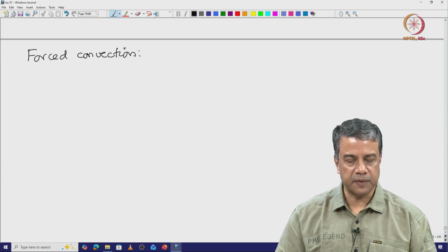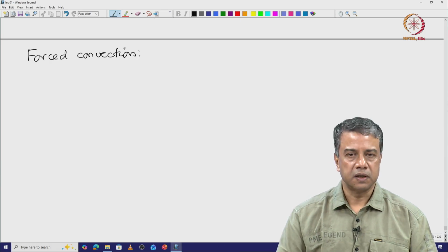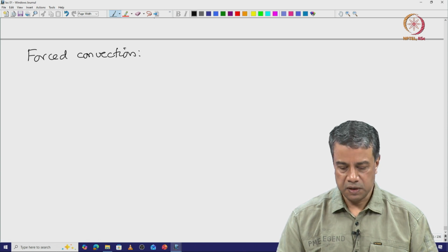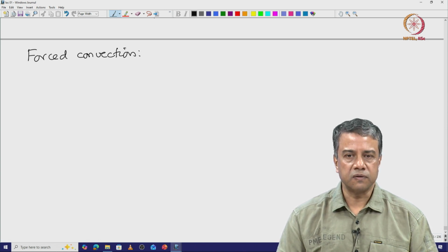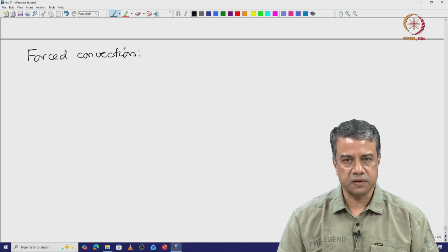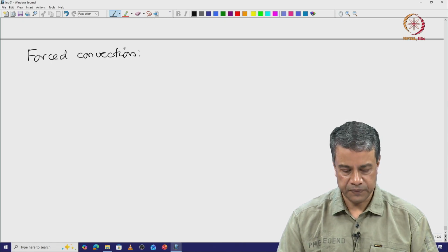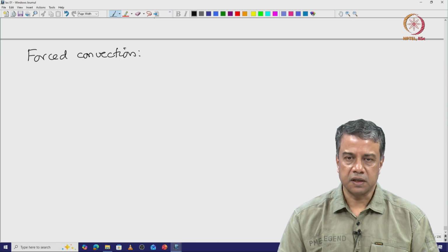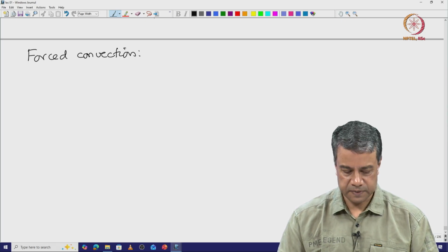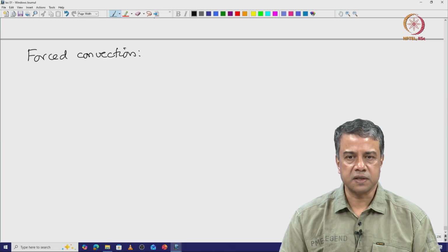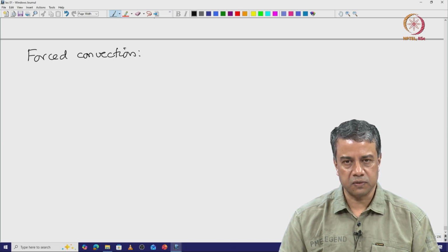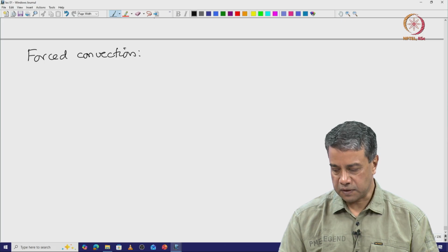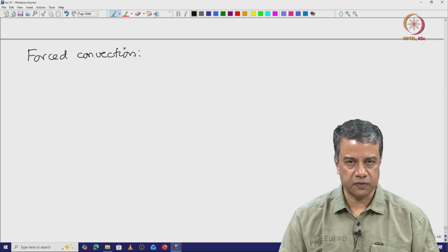In the direction perpendicular to the flow, there is no convective transport. At a surface, the flow is tangential to the surface because of the no penetration condition. Therefore, there is a flow only along the surface, there is no flow perpendicular to the surface. Heat transfer from the surface cannot take place due to convection, and therefore, heat transfer has to take place due to diffusion.